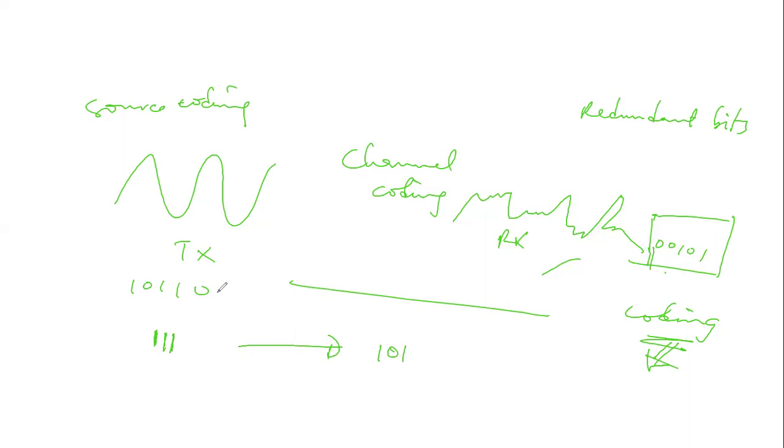This can be easily corrected. It can tell, well, if it's just one bit error, if my code can detect 1 bit in error, it can tell that 111 was transmitted. But we'll run into a problem if I receive 001. It's going to decode this wrongly and say it's 000 that was transmitted.